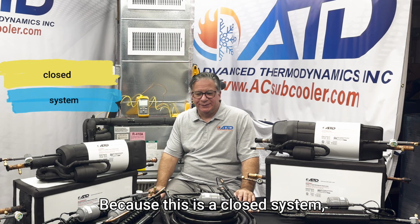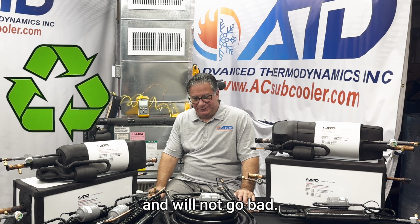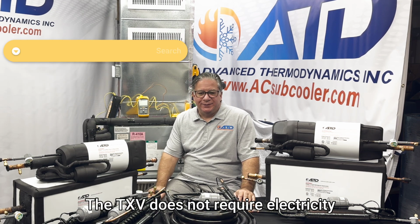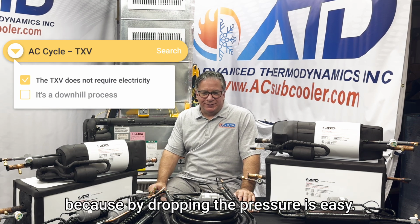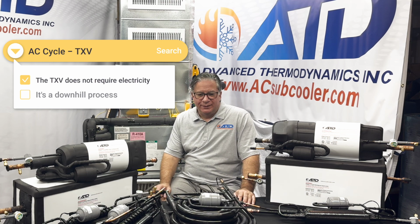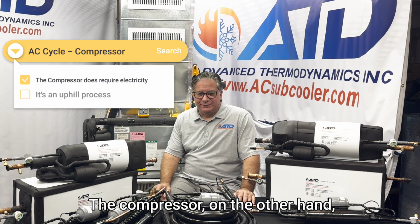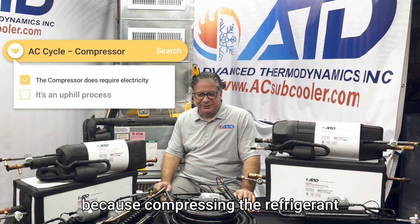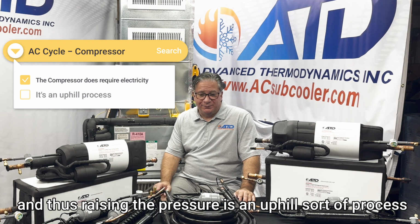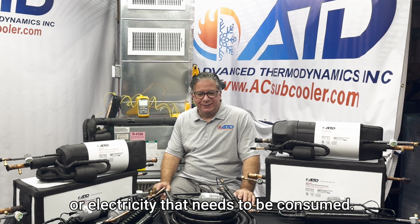Because this is a closed system, the refrigerant keeps being recycled and will not go away. The TXV does not require electricity because dropping the pressure is easy. It's a downhill process, if you will. The compressor, on the other hand, does require electricity because compressing the refrigerant and thus raising the pressure is an uphill sort of process that requires energy input, or electricity that needs to be consumed.